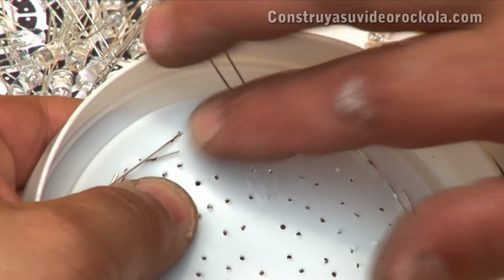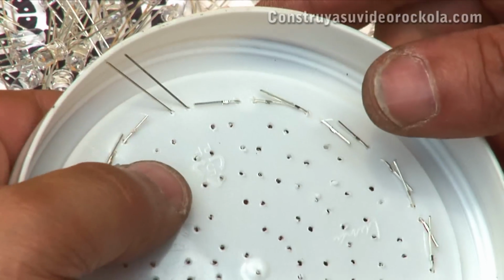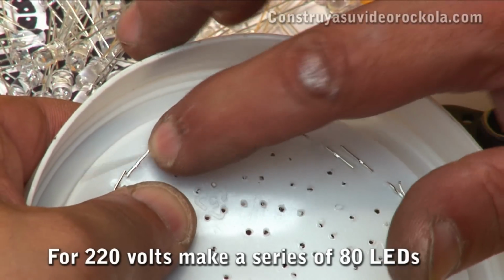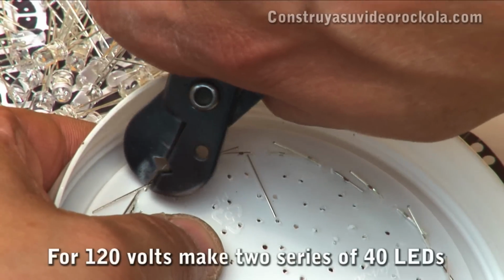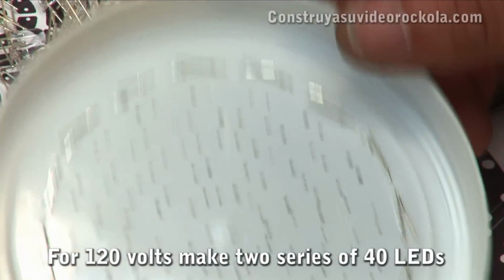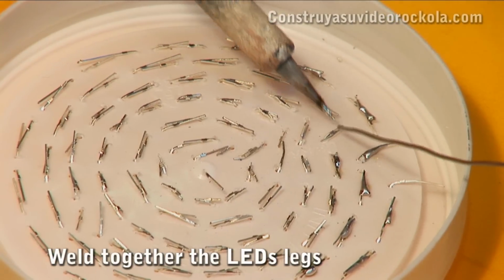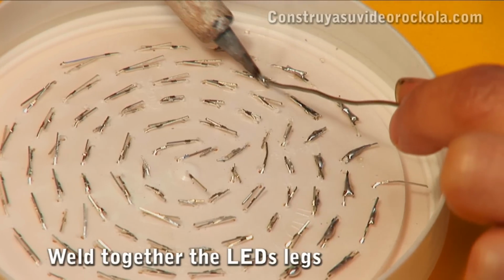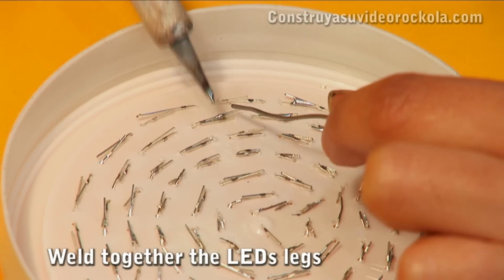At this point, we must adapt the voltage to fit our circuit. If in our country we have a mains voltage of 220, we must make a single series from start to finish with the 80 LEDs. But if we have a voltage of 120 volts, we should do 2 sets of 40 LEDs. Having made the connection of the LEDs, proceed to solder their legs, joining all the LEDs together. Be careful not to melt the plastic, make good solder joints, and do them quickly.